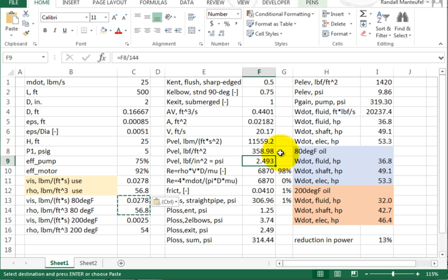It's 2.5 PSI. So we get the friction factor. Notice I calculated the Reynolds number 2 ways. They give the same number. It's just comforting to know I can use 4 m dot over pi d mu for the Reynolds number, or rho v d over mu. So then I calculate the pressure loss for the straight run pipe. How do we do that? Friction factor, length to diameter, times the velocity pressure.